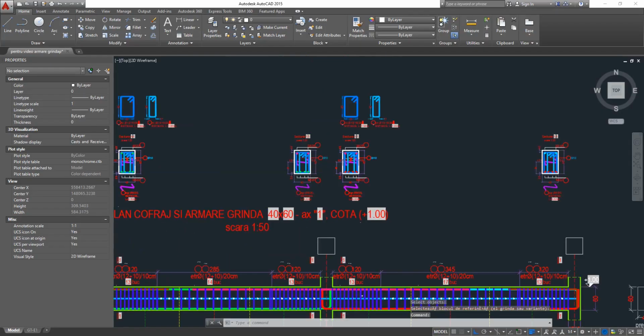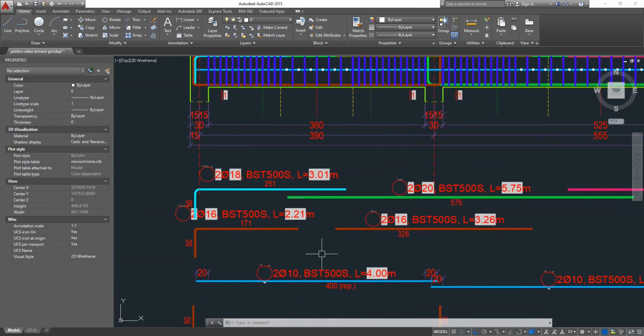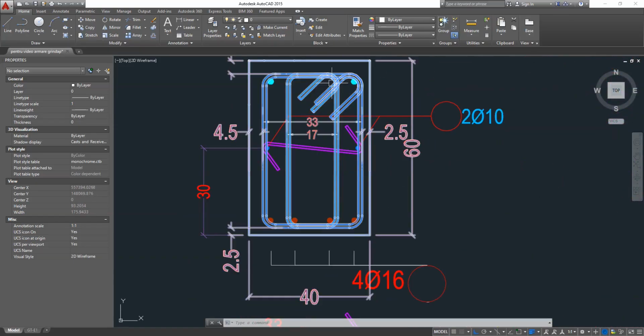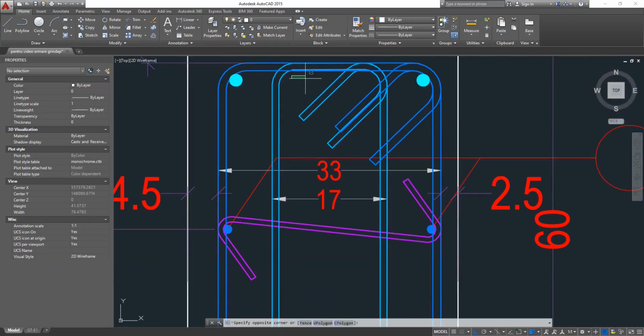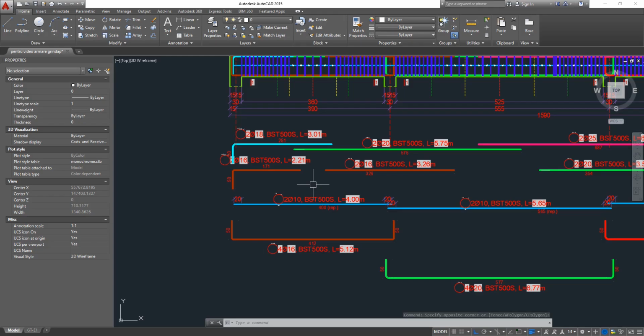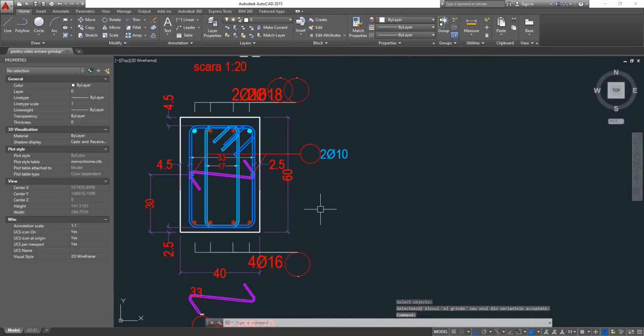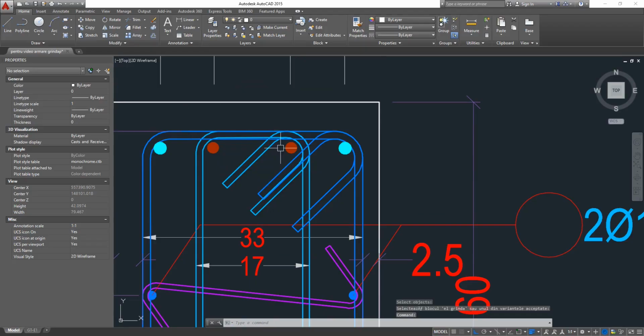Boom. And now we're going to place the second row of top reinforcement, but inside the second stirrup. Every one will be placed here for each span. Okay, so we're going to use a second special command. We're just going to choose those two, enter for this span, just hit it, boom, now they are placed, 2 of 16.